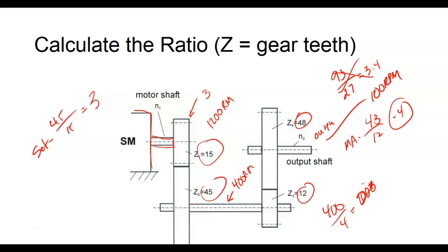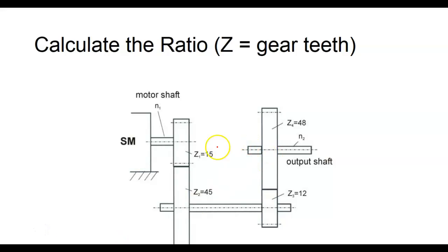So we're trying to figure out what the total advantage is. What we're doing is we're using speed. So we know it's out over in. So what's out over here? Okay, we'll call this set 1. It's 45 over 15. What's the mechanical advantage? If it's got a mechanical advantage of 3, then the speed would be equal to 1/3. They're the reciprocal of each other. They're exactly opposite of each other because we're getting the same work out that we're putting in, right?